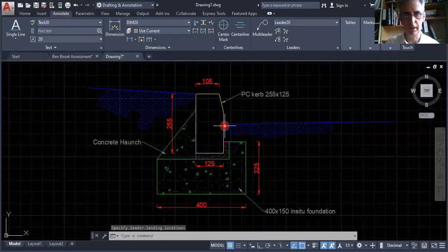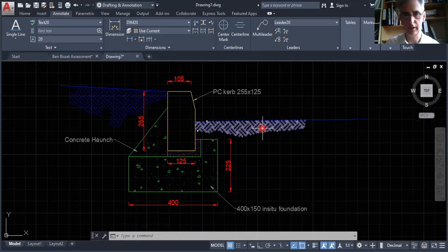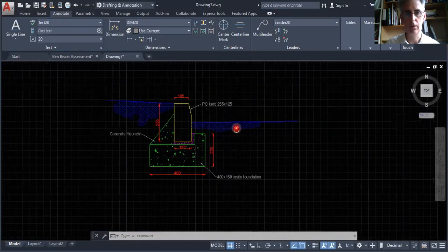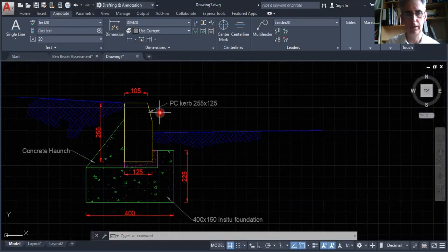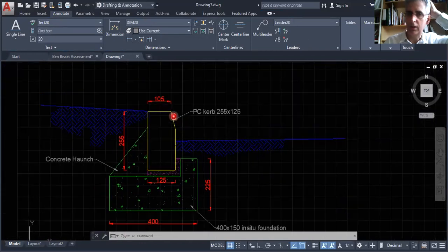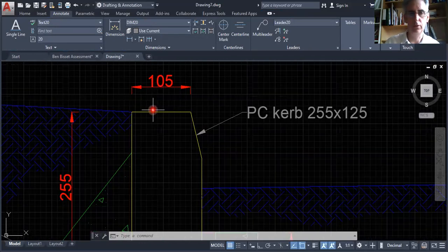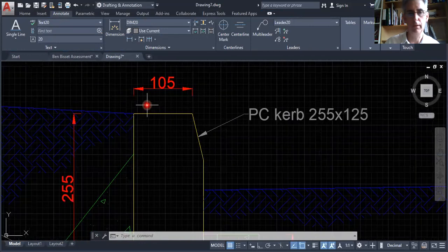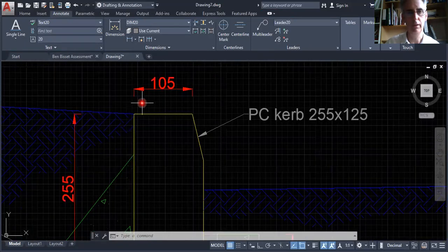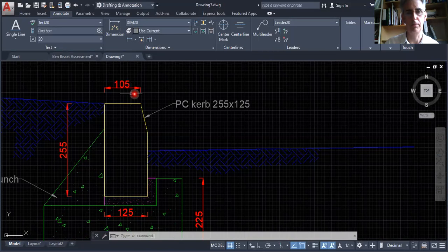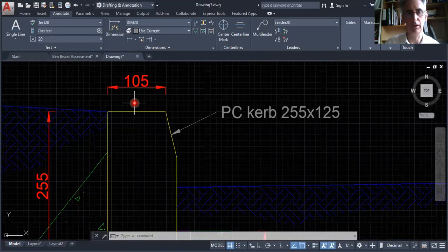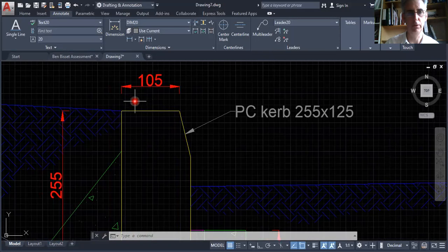And we're almost there with that particular model. We know that that's the Earth because it's hatched in that way. Okay, we could put maybe a level on this. In fact, let's do that. Let's say that this level here was going to be maybe 525 above ordnance datum. AOD means above ordnance datum. When you go to do your surveying, you'll understand what that all means. So let's imagine that sea level is 0, okay, and this could be 525 meters above sea level.